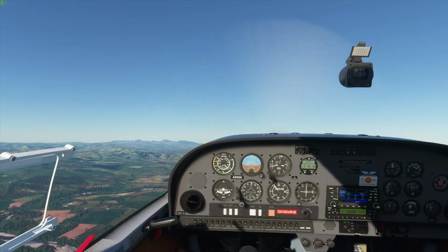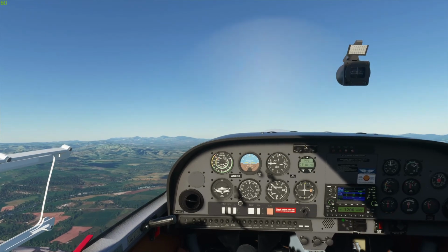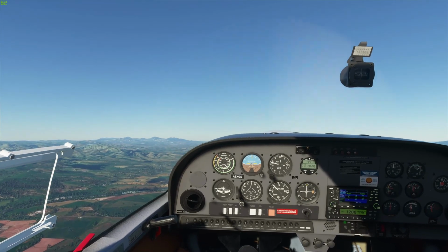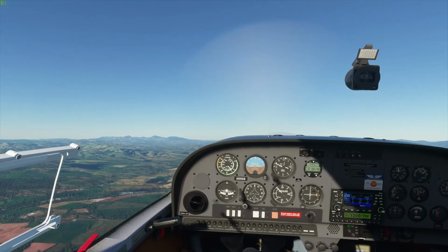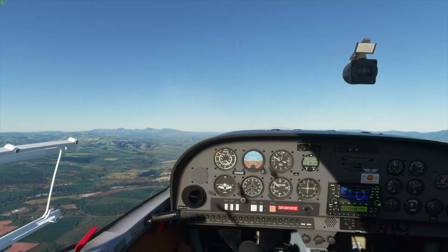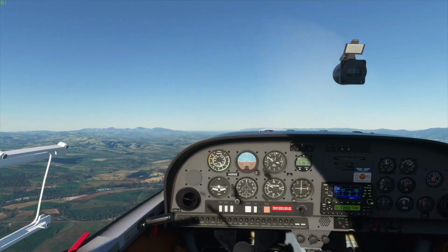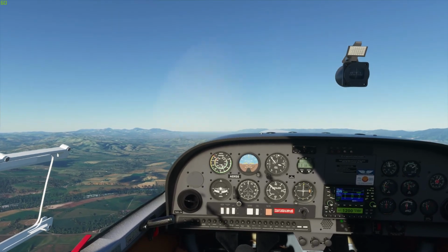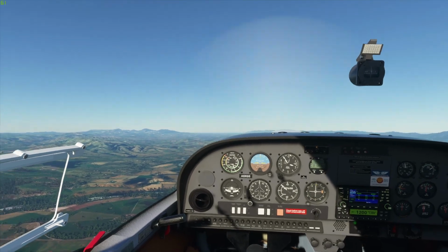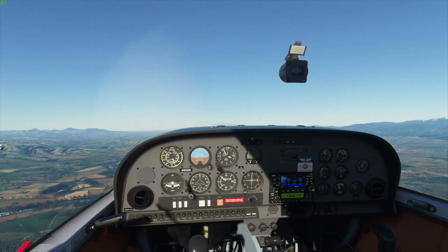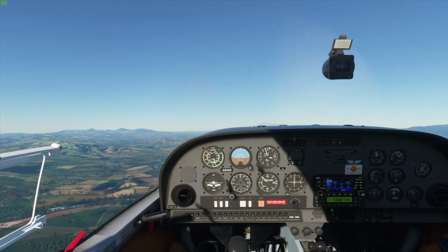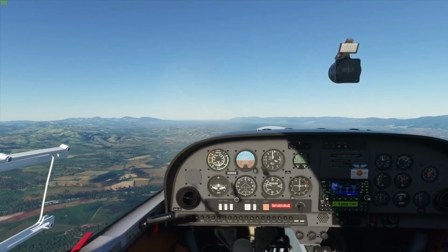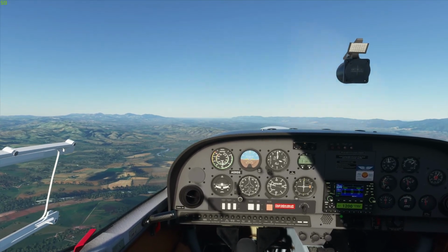docile handling characteristics. So 65 knots, still climbing, yeah, about 500 feet a minute now, so it seems to have a better climb rate between 70 and 80 knots, so we'll lower the nose and increase the speed a touch. And approaching 3,000 feet. Okay, T's and P's still in the green. So once we reach 3,000 here, there's not much inertia, so I can pretty much get to 3,000 and then level off. I don't really need to anticipate that much.